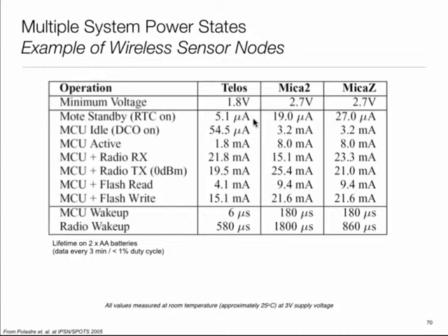Yeah, so most of the time we are on but doing nothing, right? Let's look at the next one. So all around you would see that this guy actually excels quite a bit. Okay, idle. So the difference between here and here is in this case the clock is shut off. The only thing which is on is a real-time clock. Real-time clock maintains the time. It's a very slow oscillator, 32 kilohertz usually, and that's all it is doing.